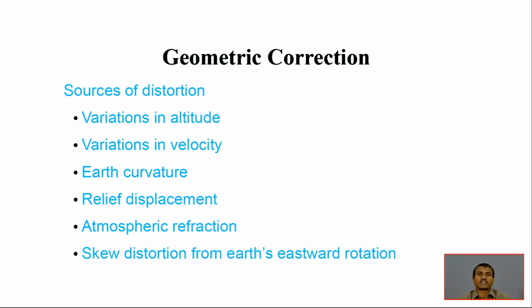The next correction factor that we are going to apply is basically the atmospheric correction, refraction. I already told you that there are two kinds of refraction that are going to play. One, the amount of sunlight you are going to receive, and also when the sunlight is reflected back on the return track to the satellite sensor. As the atmosphere is a gas, and in gas there is a density difference, due to that the light is going to refract in different directions, and due to that some amount of error is also going to be contributed. So, you have to apply some amount of correction.